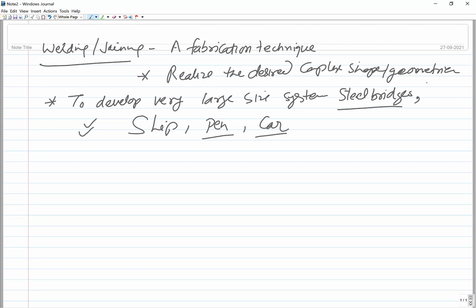Okay, sometimes joining is needed just for good reliability. Like an aluminum copper joint can be simply developed by just twisting them, but the reliability may not be good. The joint may get opened after some time. So if you have to join two dissimilar metals, wires of say copper and aluminum, which are not really compatible with each other, you have to use something which will bring them together, and at the same time the sustainability, the life and reliability of the joint will also be long.